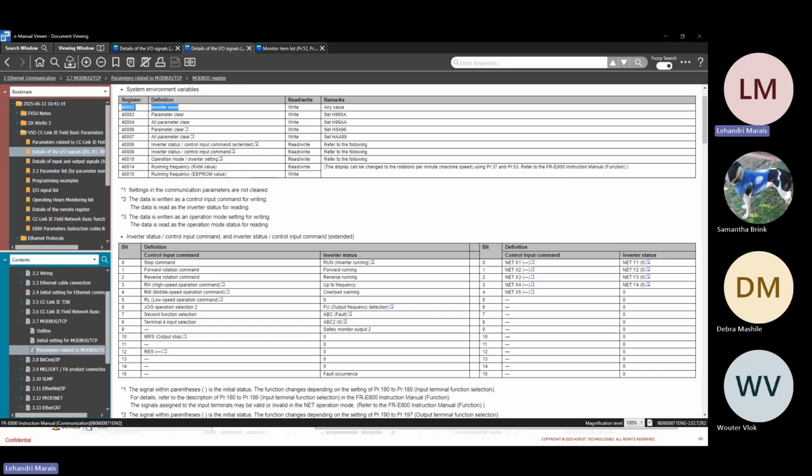Whether this is setting a frequency or activating one of the run high, medium, or low bits, you need to give it a speed reference. For this demonstration, we'll once again be setting a frequency, which you again have two options for.